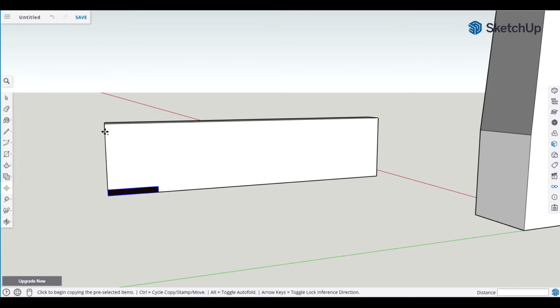Well, we're going to hit the escape key, and let's try it again. So we're going to hit M for move. We're going to click the top, and then we're going to move it. Hit the control key, and then snap. Click once, enter, slash. So we need to create 3 more, including the one we moved. Enter 3, boom. We now have 2 in the center.